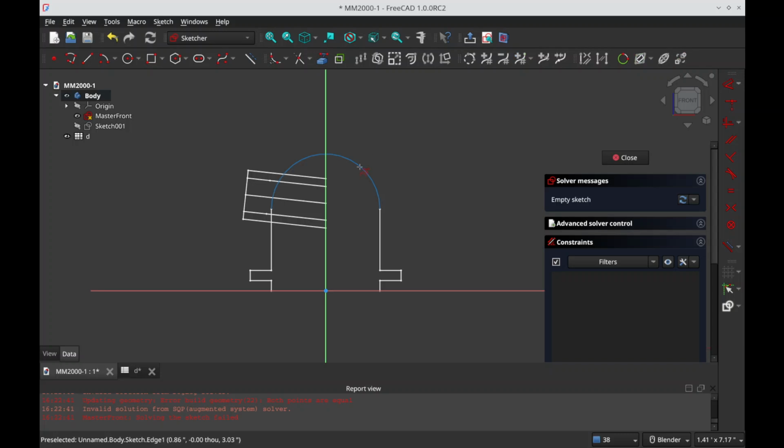So bring in external geometry here, bring all of that, and we're not going to do the actual shell just yet, because my thinking is it'll be a lot easier to do the shell last, after everything else is done. That way we don't have to play with depths of extrudes. Everything can be extruded out from here and just be a bit easier.